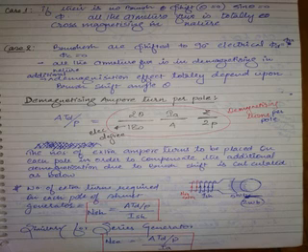Demagnetization comes with the theta. So theta is the problematic area. On the top and on the bottom, total you will have 4 theta. So this 4 theta region is out of total how many degrees? 360. If you observe, demagnetizing ampere turns per pole.